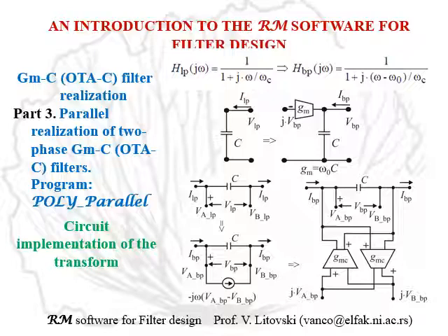So in the next line we have on the left hand side a capacitor in a low pass in the original circuit. And what is on the right hand side? We have this capacitor to which is brought a signal which is first shifted by 90 degrees, that is j, and then multiplied by minus Gm.